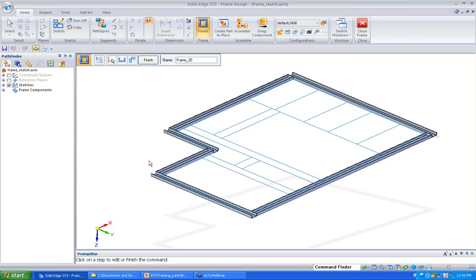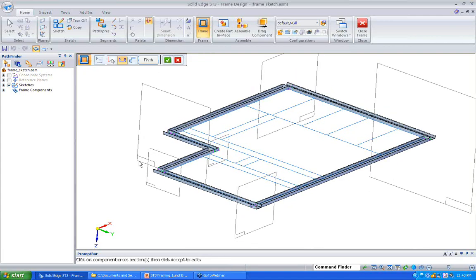If you want a specific type of corner treatment, the next step is modify end condition. Maybe I want to modify the end condition here on this intersection. I can select the point and then give it a condition of miter. It will only affect this particular joint, keeping the others defaulted to the global setting. Right. So now we will change some cross sections here.